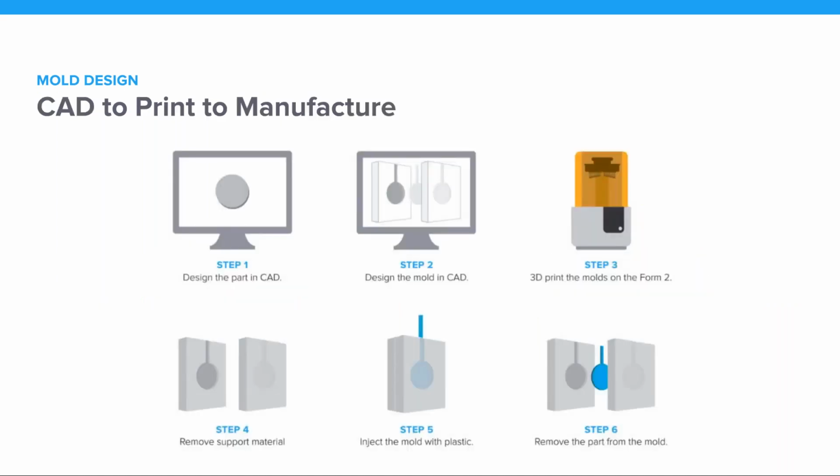So in terms of the overall process, this is kind of the steps. Step one, design, print, put in the injection molding machine, inject, and you have your final part. If you'd like to use a standard aluminum frame, you can get those from an injection molding manufacturer. They're very common. You can have them custom machined by some other agencies. It's not super expensive. I think for like maybe 4x4 it might be under $300.